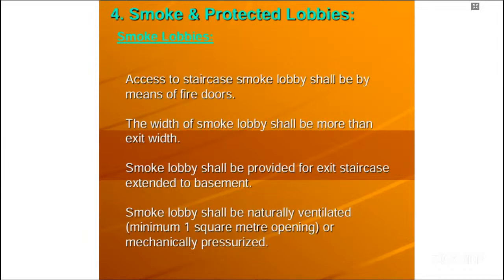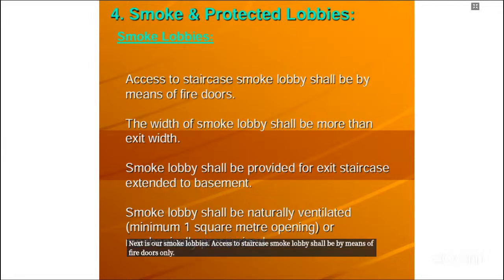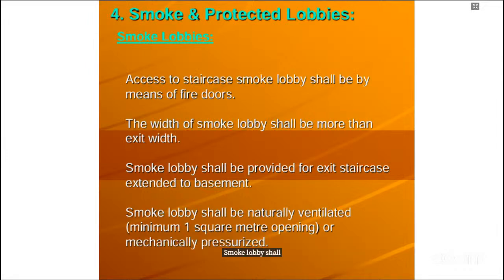Next is our smoke lobbies. Access to staircase smoke lobby shall be by means of fire doors only. The width of smoke lobby shall be more than exit width. Smoke lobby shall be provided for exit staircase extended to basement.